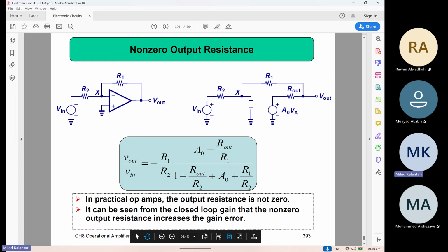So the final, I guess this is the last one. Which we already knew a little bit about, is the output impedance of the model. We were always assuming that the output impedance is 0 initially, but we know that everything that we make actually has some limited output impedance. It cannot be 0. So if you draw the model with the output impedance, then you will figure out that some of the equations need to be modified.